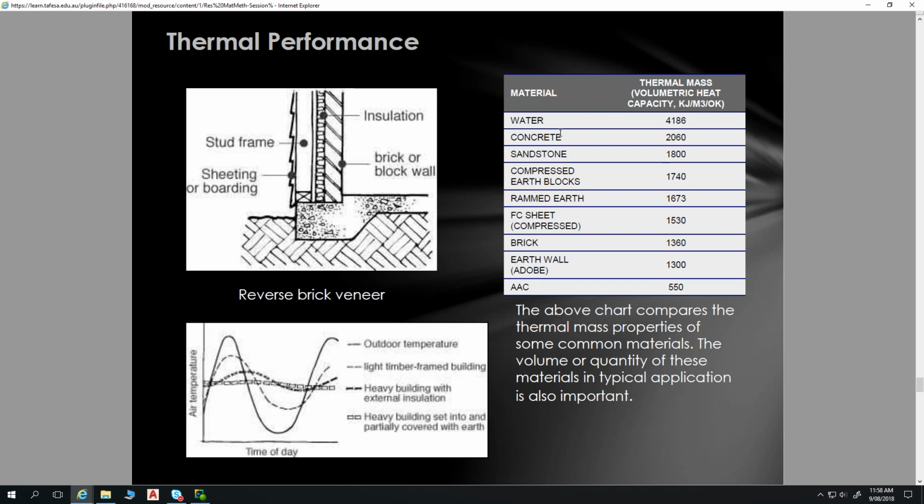People who've done that. But it takes advantage of that regular temperature of the earth and the overriding thermal mass that earth has. But we can think about the thermal mass of our various different materials there as well. And this one here is called brick veneer. Now we spoke about, that's reverse brick veneer. We spoke about brick veneer earlier. Our timber frame and then a gap, and then our veneer of brick on the outside. Reverse brick veneer flips that all around.